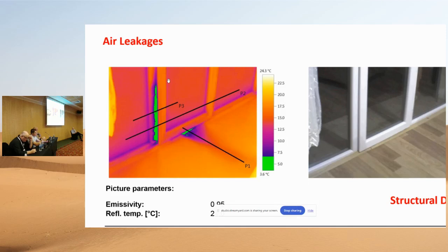If you apply minus 50 Pascal or plus 50 Pascal, pressurizing the building positively and negatively, you will directly see, even with a naked hand, you can feel drafts coming from cracks or from improperly installed gaskets of the doors and windows. You will be able to see the same structure.